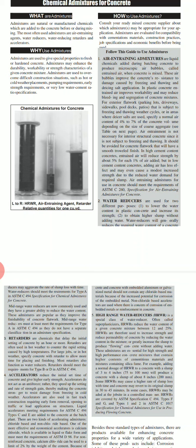If the water content is more, what happens? The strength is going to be reduced. That should not happen in a concrete. So to take safety measures, we add water reducers. They reduce the water content and increase the strength. This is the first objective.